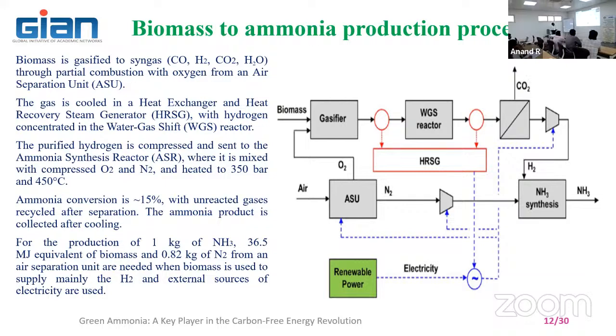So even now we are suggesting that in the engine, instead of supplying air into the diesel engine combustion or petrol engine combustion, if you put some kind of air handling system before the filter or after the filter, you can separate out oxygen and nitrogen. If you send only the oxygen into the combustion of petrol or diesel in the engine, there is no possibility of oxides of nitrogen coming out. But how to separate out oxygen and nitrogen very quickly to take care of the demand of the engine, that is a big research question.